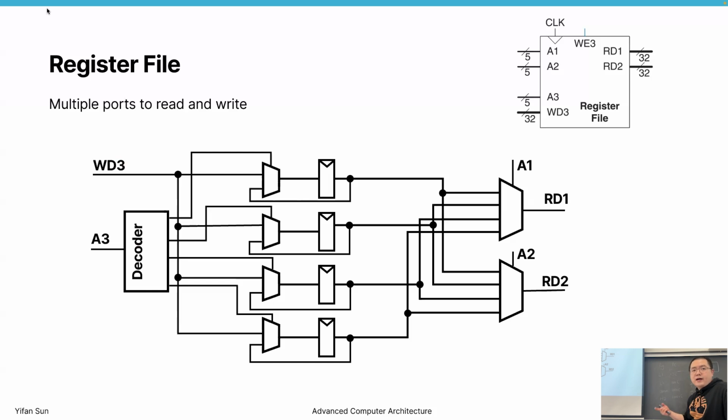When the write is not enabled, we keep the data the same. We don't do anything. This circuit is a little bit complex, but you can parse it as 3 parts: the read logic, the store logic, which is the loop back, and the write logic.